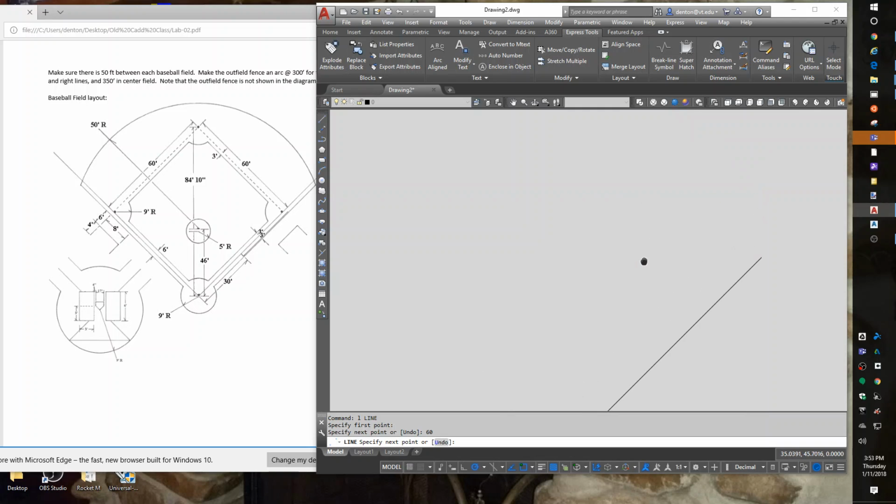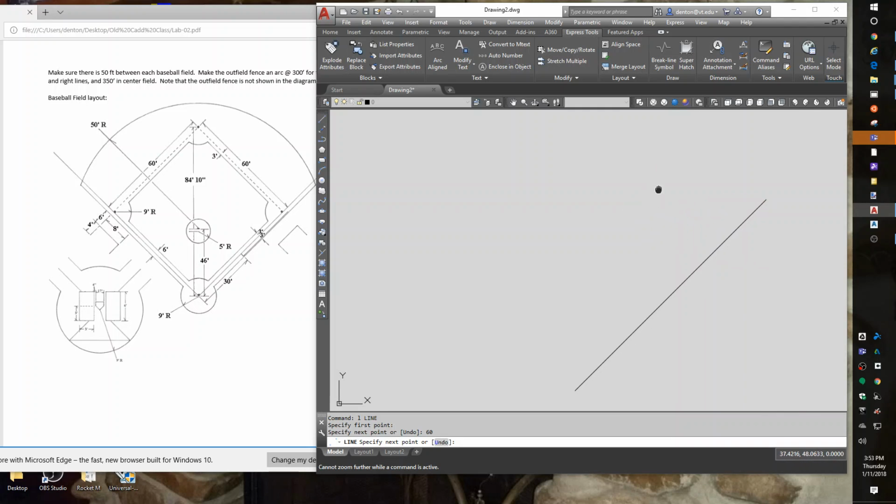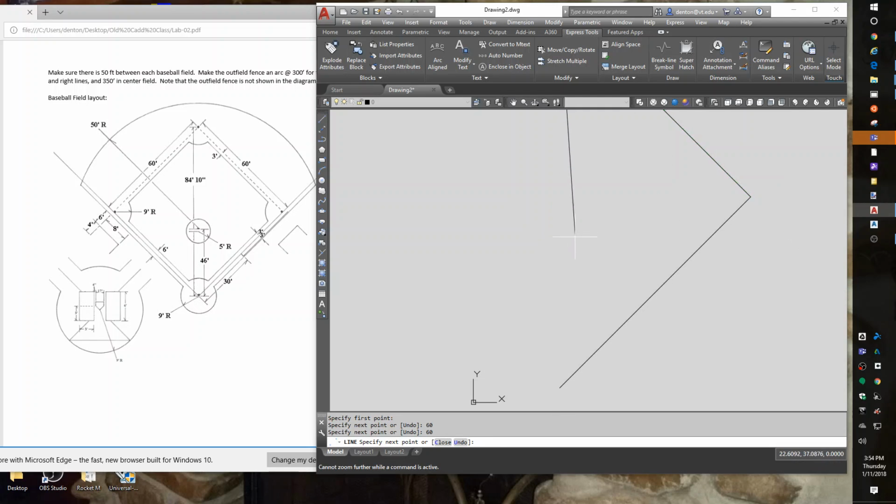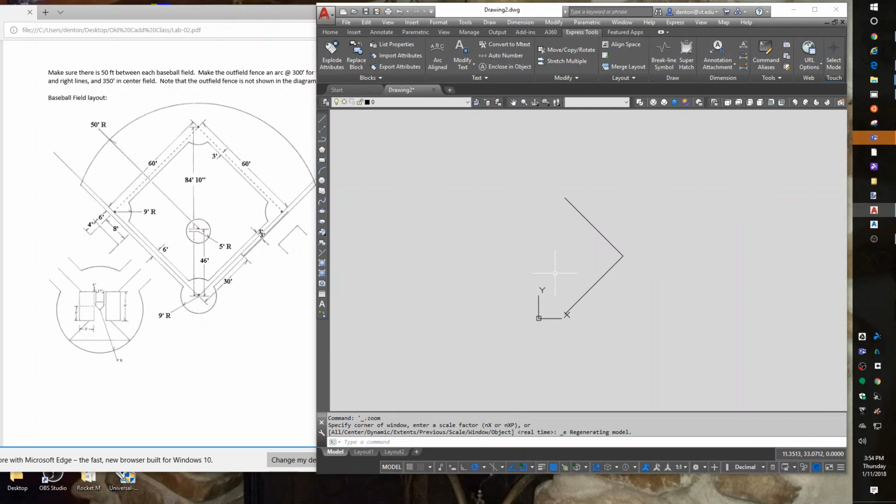If it doesn't roll out far enough, we can zoom extents to make it go further. I'll show that on the next one here. I'm going to go to the left, 60. I roll out, it doesn't go. I'm going to hit enter to get out of the line command. Double click the wheel, does a zoom extents, which resets my zoom ratio, and I'm good to go again. Go on a 45, 60 feet, back to my starting point.